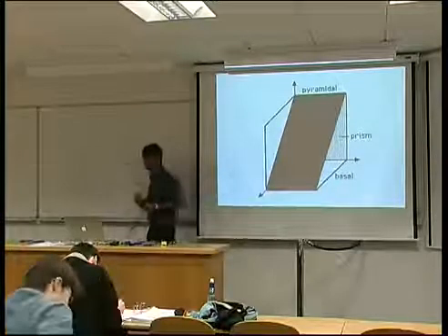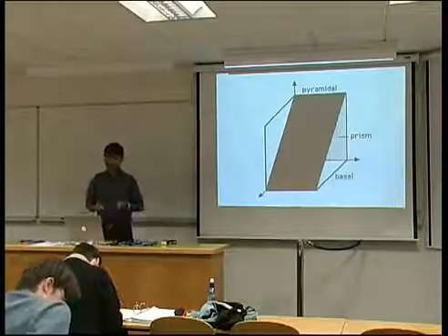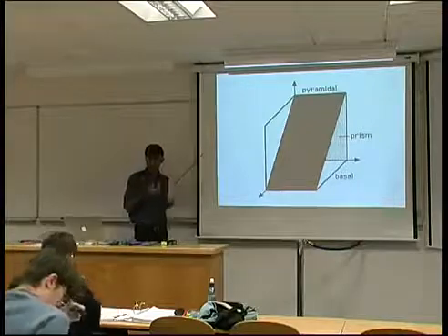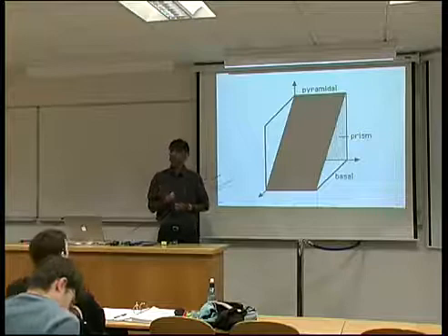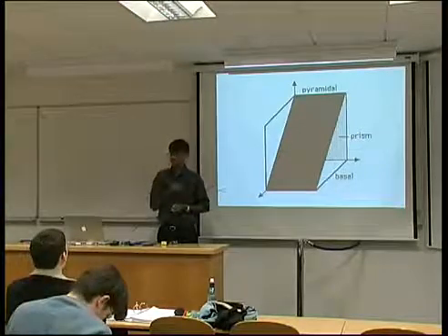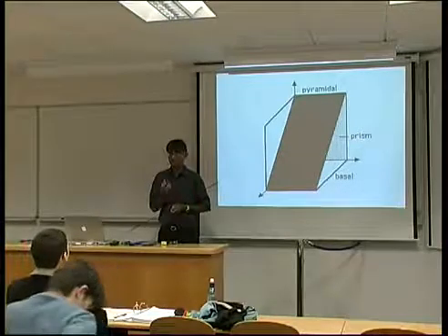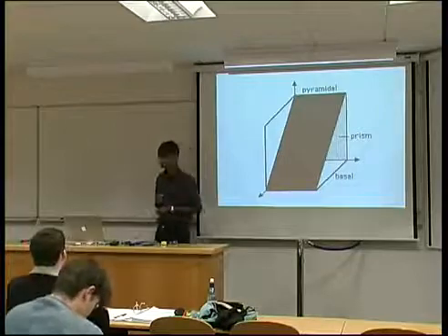It's because of this distortion of the C upon A ratio. So alpha titanium, although it doesn't have the same ductility as a cubic material, you can deform it.